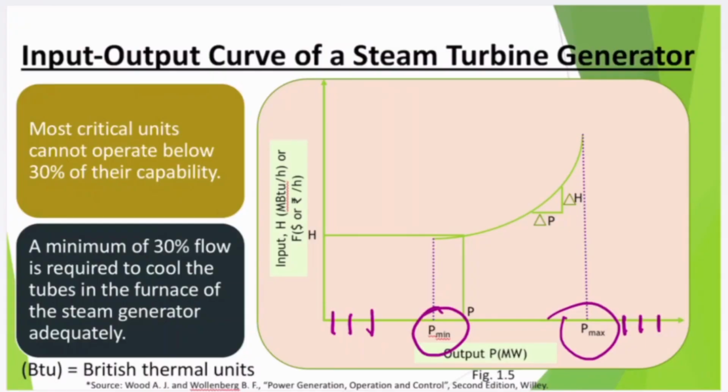If I say that my machine is rated at 100 kVA and my reactive power generated is 10 kVAr, then from those two, the volt ampere and the kVAr, I can calculate my kilowatt, and hence the P generated cannot be 100 watt for a 100 volt ampere machine, because there must be some reactive power at all times.